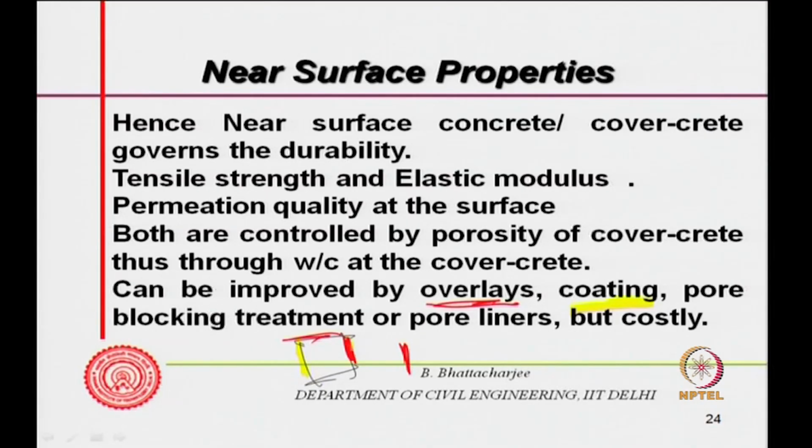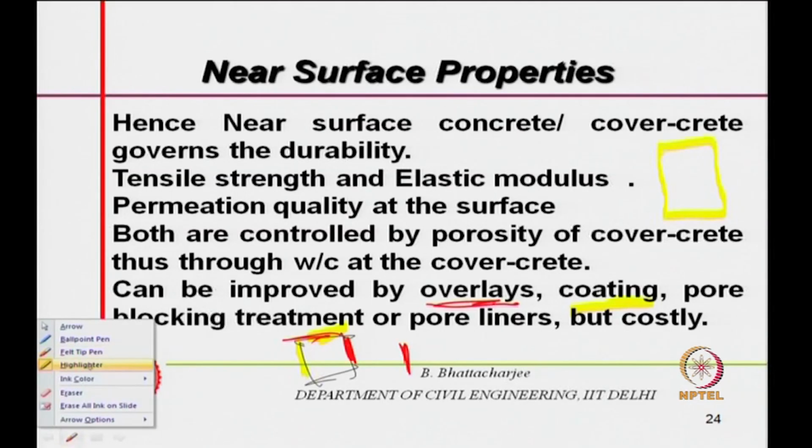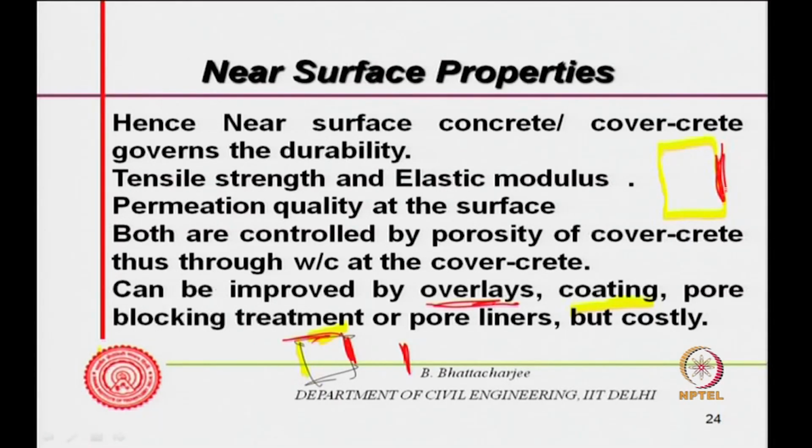Pore blocking treatment, or pore liners, are actually waterproofing treatments. I might add waterproofing admixtures into the concrete. Also, I can use a material applied by brush onto the concrete surface, and this material penetrates inside.